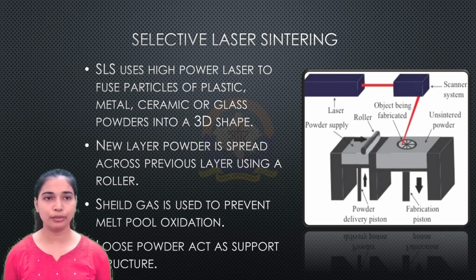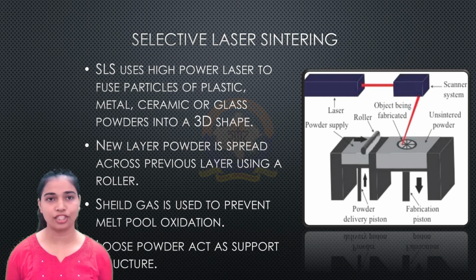It is a commercially new technique and is used for manufacturing of small stock components, though various sectors are approaching the technique as there is an enhancement and development in this domain. SLS printers use a high power laser, for example CO2, to fuse powders into a 3D shape. The laser selectively fuses powder material on the powder bed by scanning the cross-sections generated from the CAD data.